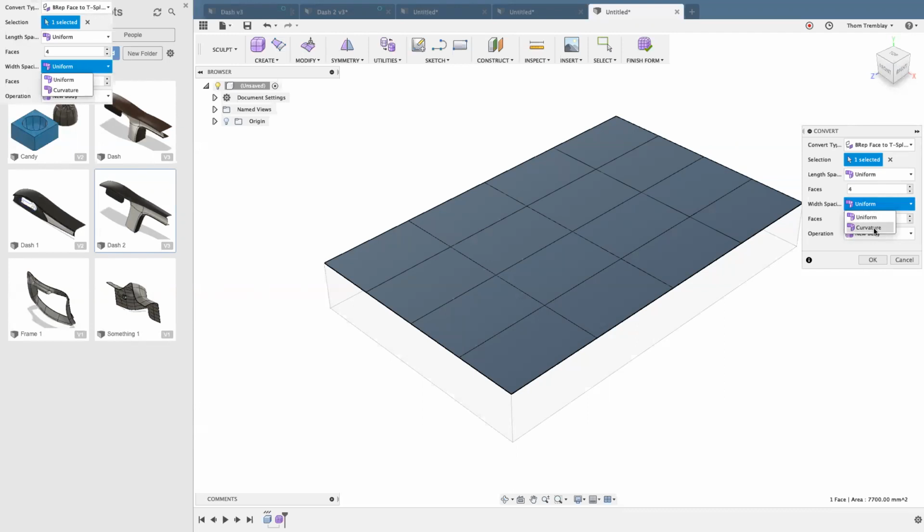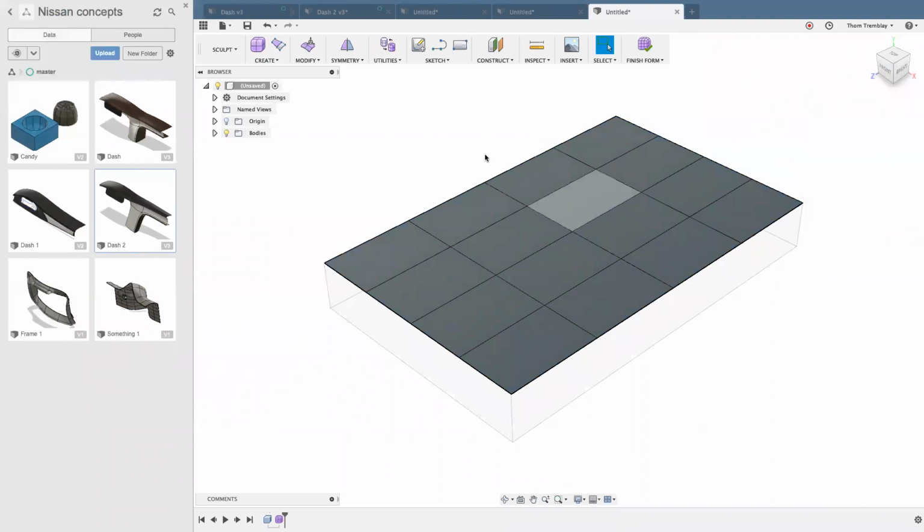Let's say you were already used to using some of the typical Inventor or SolidWorks workflows where you're doing lofts of solid models. If you're already comfortable with that workflow and you've started to create your design in that way, and now want to just give it a little additional detail or add some shapes that are just going to be too difficult to get from your loft, you can go ahead and use these curvature options. For now, I'm just going to leave this a nice flat face.